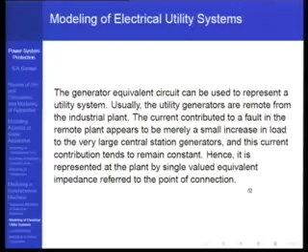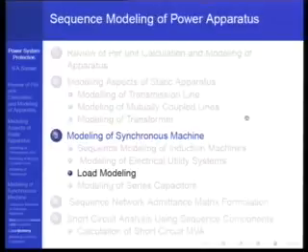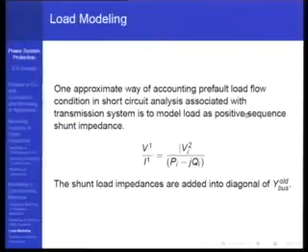Electrical utility systems, you would take as constant impedance. I mean, if the fault and the utility are far away, in that sense you are a fault on a distribution side and then the transmission sides and all that, generators will only see a notch addition in the current, so therefore the outside utility system can effectively be modeled by a constant impedance for positive, negative and zero sequence.